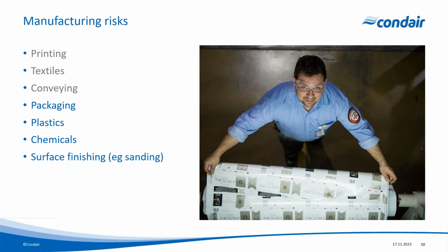And if we've got a negatively charged pharmaceutical and a negatively charged blister pack, then there will be a repulsion there. And the speed of that process and the quality of that process will be dramatically affected as the tablet doesn't drop into the blister pack correctly. Again, it depends whether it's negative or positive, and the effect will depend on the materials.